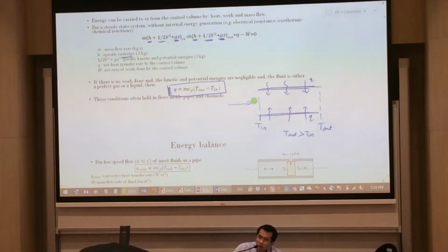So it will gain that amount of heat. The amount of heat that it gains as it flows through is equal to the amount of heat that you put in radially into the fluid. So later on, you get to see that we need to equate these two equations. One of them would be the heat that's transferring in, and here it could be via convection, because convection is where heat can get transferred from the solid to the liquid, or the fluid, over here.